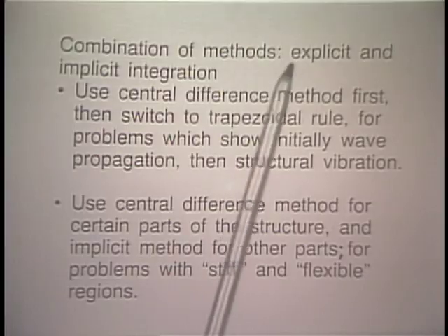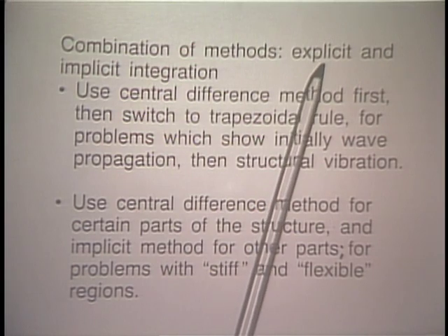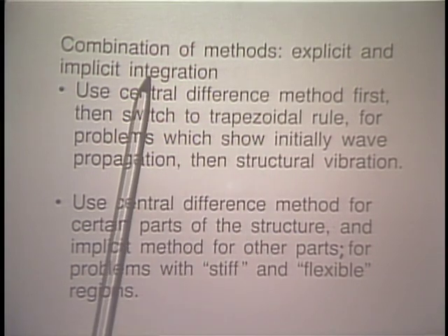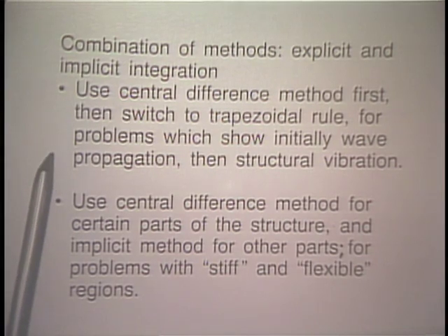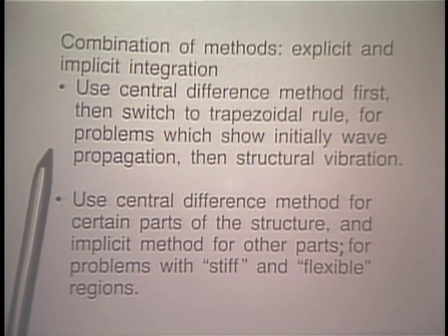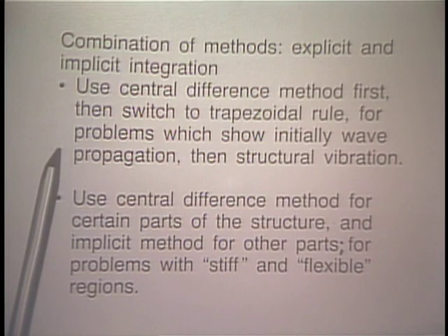and what one would look for to make sure that you have adequately calculated the response. Finally, I would like to also point out that it can be effective to use the combined technique of explicit and implicit integration. You might, for example, have a problem that shows an initial wave propagation and then a structural vibration.